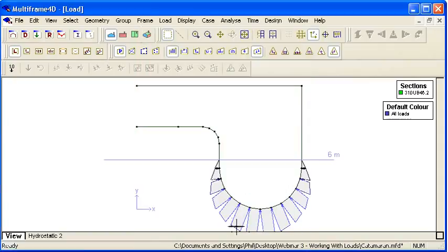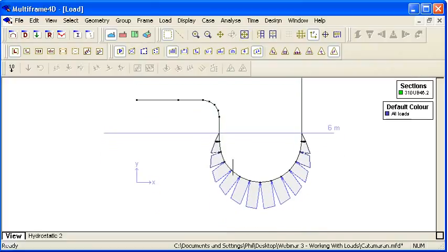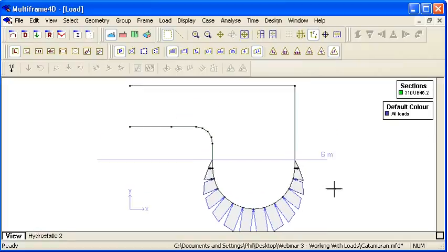So if I do that, we can see that what happens is our waterline is drawn and our hydrostatic loads are automatically applied to the structure. So what I've got here is a cross section through a catamaran of a ship, half of a catamaran, and you can see that everything below the water level automatically is applied a load based on the tributary area between frames of the vessel. And we can see the values which are calculated there. So if I modify any of my geometry or what have you, all of my loads will update automatically.